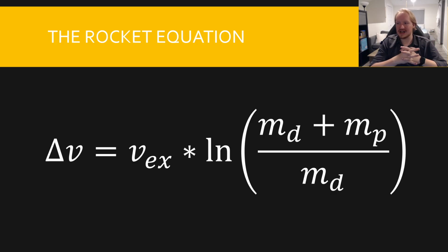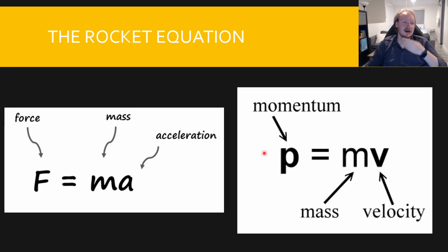When you do trajectory calculations, NASA has a good website for them, or when you do them by hand, a lot of the time you're talking about what's going to be our total change in velocity. Can we have an engine that fits that? If we can't, how can we change our orbits, change our trajectories, so that we can get there in a timely manner with this lower delta V limit? This is a very, very important type of equation because we can find how far basically our spacecraft can fly.